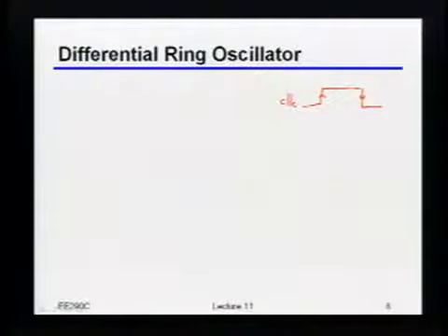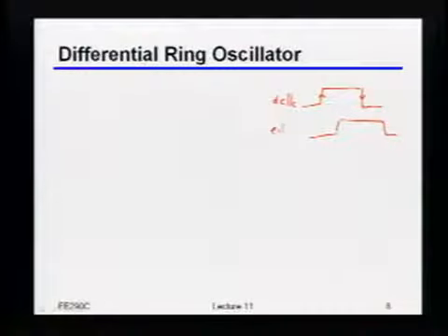But if you think about what it would take to also recover the timing information, that would mean that you'd also need a quadrature clock, because this would end up being half a bit time away, that would be, let's say, t-bit over 2 if you do the quadrature clock there.